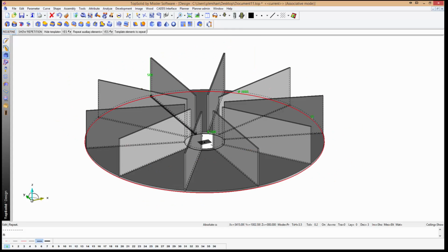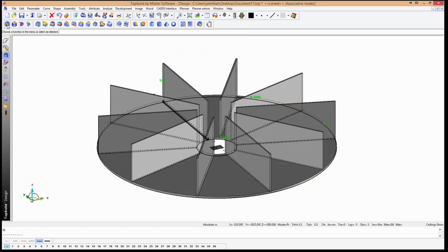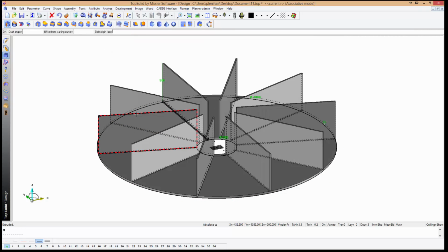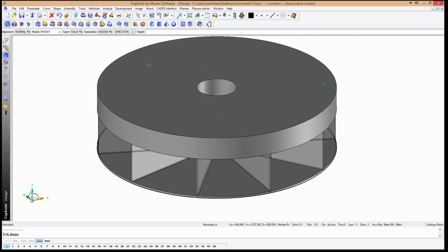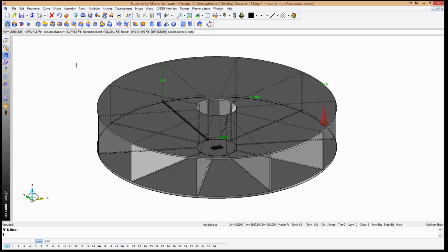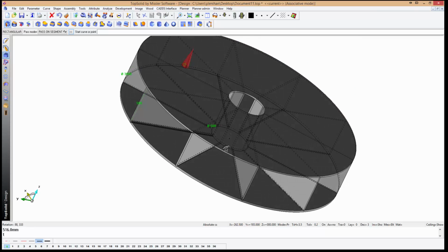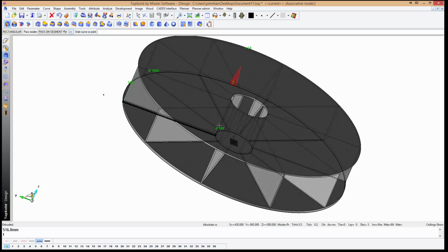So quick, so easy. So let's now create the top panel and skins. Okay, top panel. Once again, I'm just going to click on perhaps the top of this panel here. And let's say it needs to be whatever T is, the thickness of my board. There you go, finished. Now let's create the ends or the skins that we want on the inside but also on the outside of this joinery piece.